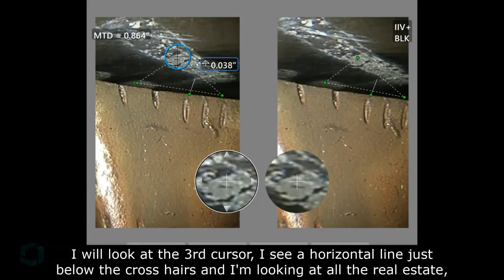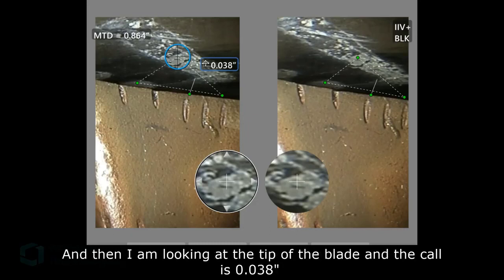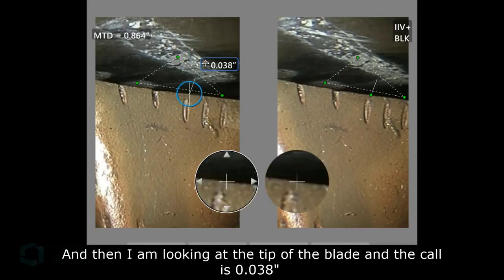I see a horizontal line just below the crosshairs, and I'm looking at all the real estate, the pixels that are surrounding that cursor, to do everything I can to verify pixel matching. And then I'm looking at the tip of the blade, and the call is 38 thousandths.